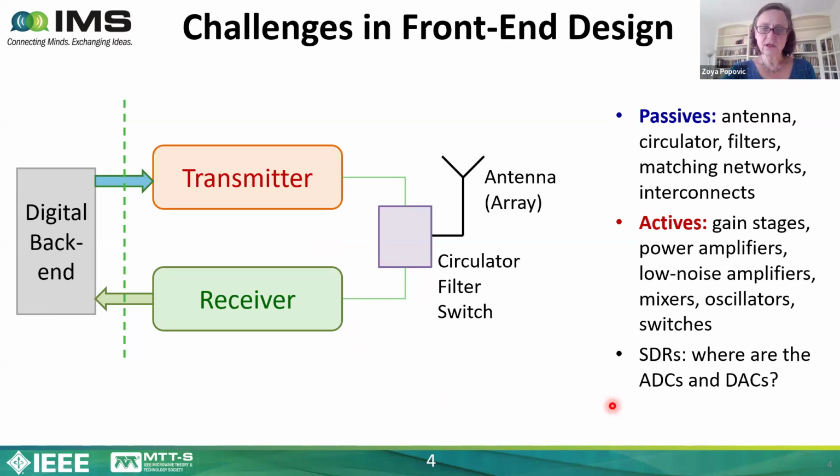So the question is, where do software-defined radios come in here? Ideally, people would like to just eliminate this analog front end and sample directly digitally after the antenna. And that can be done. The problem is that often it's accompanied with either a very reduced dynamic range or with increased power consumption. And so it turns out that for most high performance current front ends, there is an analog part, and it's what I'm going to talk about here.